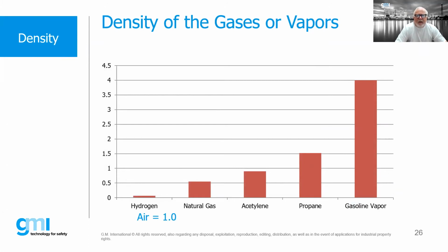A lot of times people wonder, if you pull into a petrol station, a gas station of some sort, and you look right above you, gasoline vapors are extremely volatile and flammable. But you'll see that gasoline vapors in this chart are heavier than air, meaning that as we fill up our vehicle, any of those vapors are going to go to the ground. So when you do area classifications for, say, gas stations, you'll find EX equipment maybe near the ground.